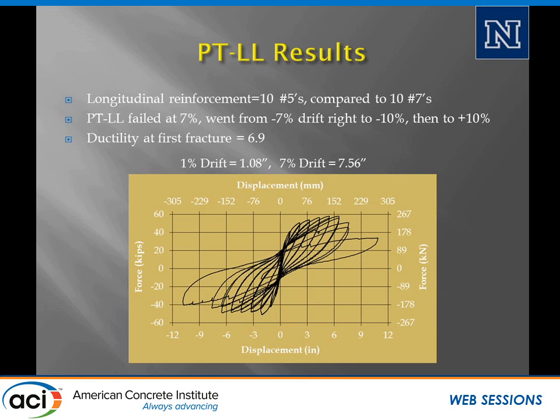You'll also notice that this is load versus displacement. That's not coming back through the center. And it's not coming back through the center because we have a combination of conventional reinforcement and post-tensioning.